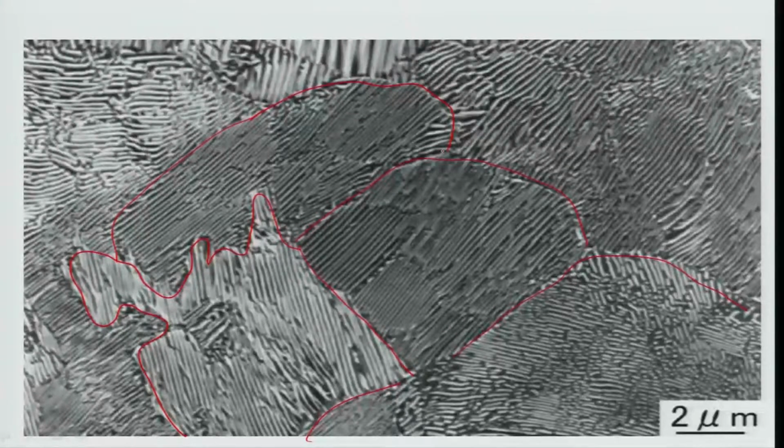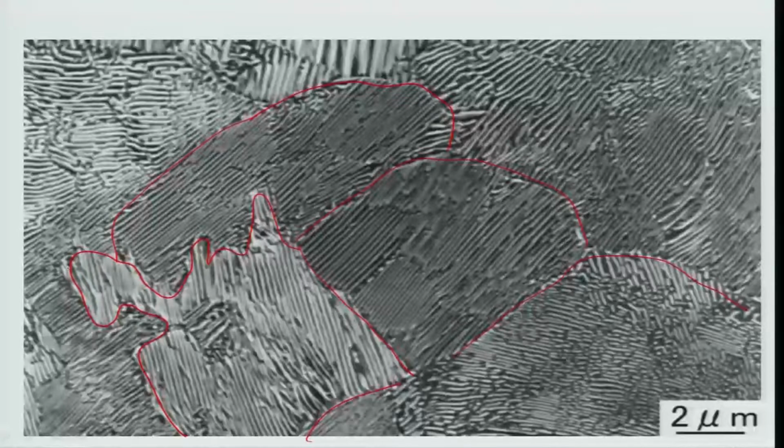white regions. So, what are these black and white regions? The black ones are basically cementite and the white ones are basically ferrite. And this black and white contrast happens because of the etching we use. We normally use nital, which is nothing but nitric acid, to etch it, and nital preferentially reacts with cementite, and the cementite regions go away, and that is why you form the black regions. So, that is normally the microstructure of eutectoid steels, or 0.8%